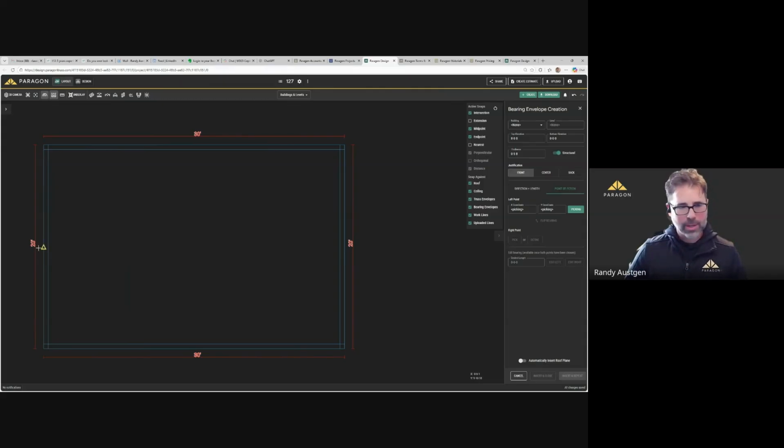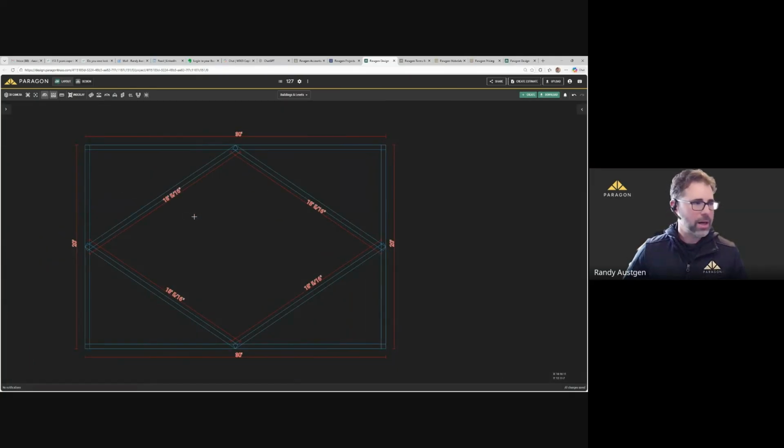What I'm going to do this time is I'm actually going to hold the Alt key on my keyboard. I'm going to switch this to back. We're going to create some art here, and we can see that by holding Alt, my previous endpoint becomes the new start point. So here we are. Look at that. Isn't that fun? There we have it. Escape to get out of there. So again, to get into that repeat mode, you can hold down Alt. That's also available when we're putting in planes, and we'll touch on that there as well.